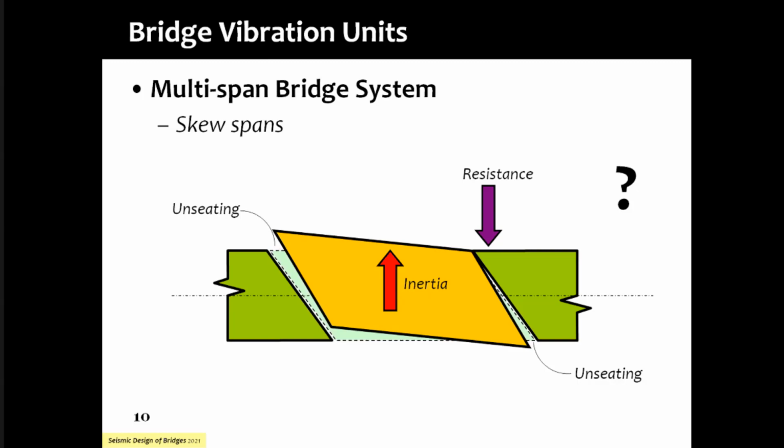You will notice that the more exotic the spans, the more challenging. We just saw one skew bridge across the railways, and if you're going to design the bearings the same way as you design normal straight bridges, then we are going to definitely have a challenge of unseating, and that is why we need special attention on the orientation of the bearings, and in particular the design forces on the bearings, right?